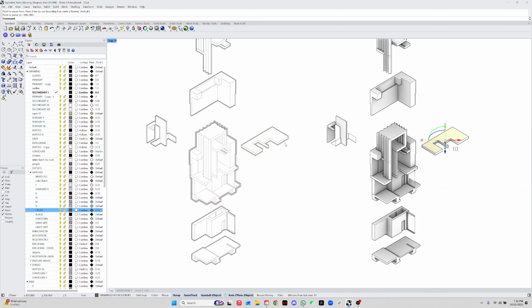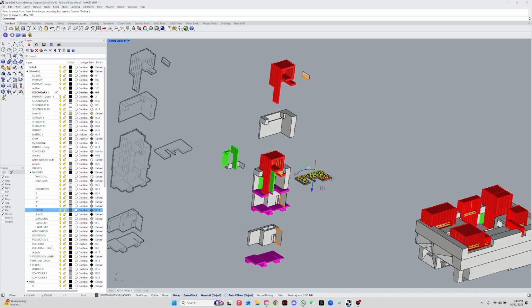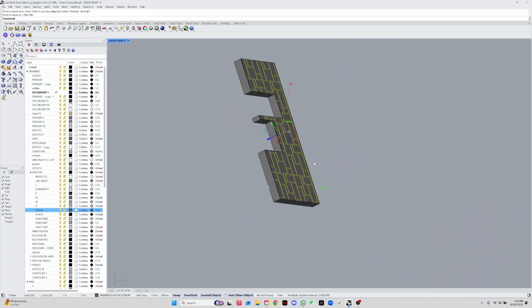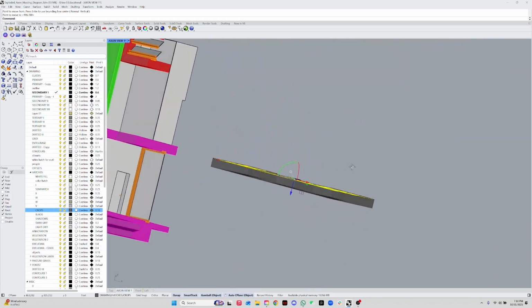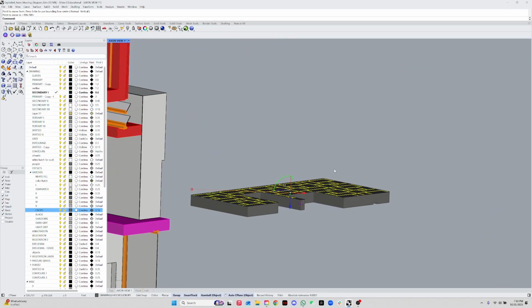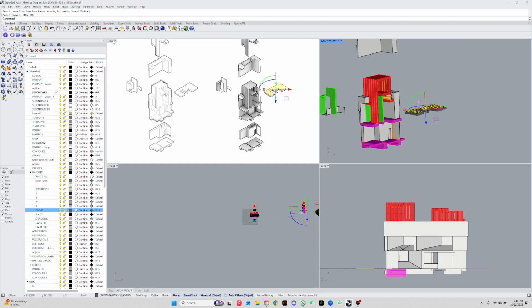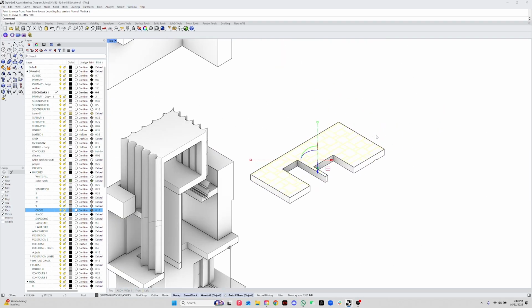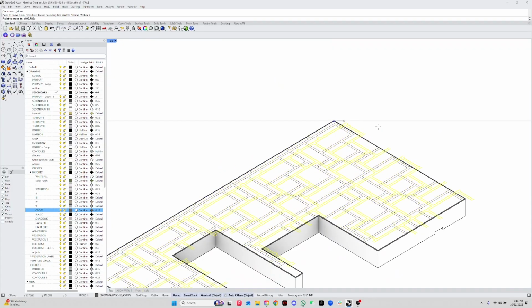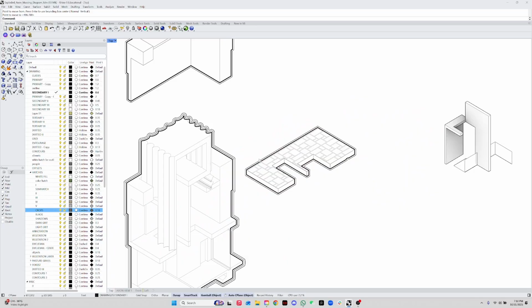But before I do that, I want to show you that if I go 3D, I can see the hatch mapped into the surface, right? So that's the angle that I'm getting. I'm not getting a flat hatch. I'm getting an angled hatch that goes with the geometry of the 3D model. So it looks to its original shape and view. So I'm going to grab that, put it here. And then now I have my hatch there, right?